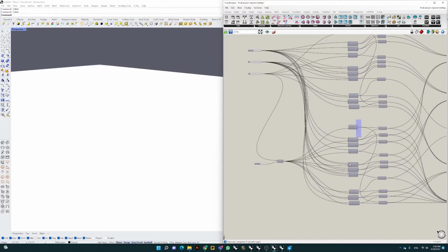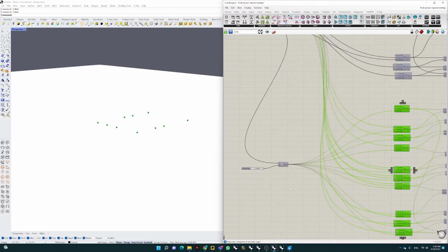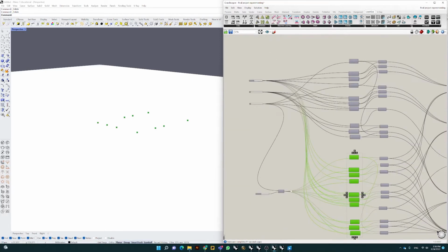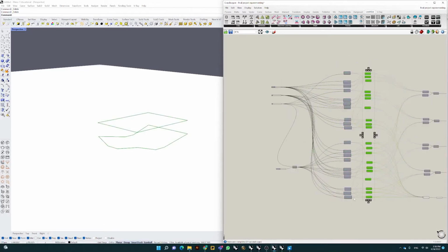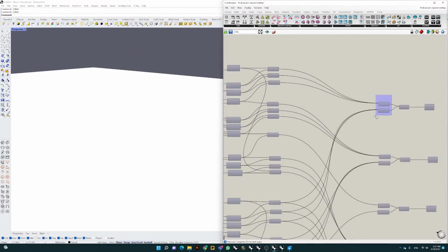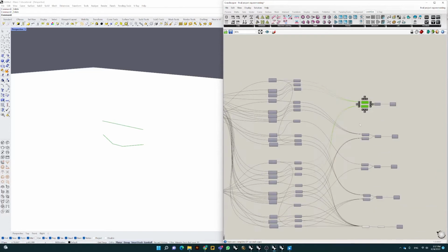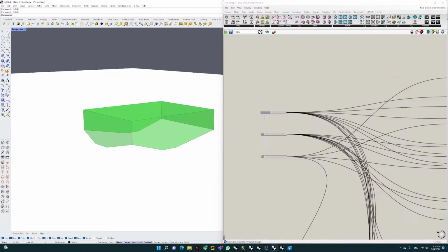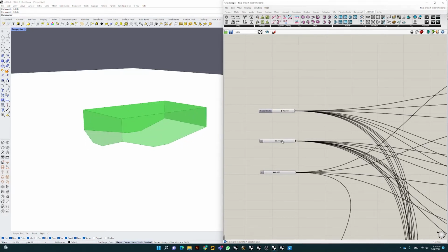And then for the bottom part, we also use the same method, but for the z-axis, we actually took the z parameter and then multiply it by 3. So there is going to be a relationship between the height of the building and the height of the openings on the mass. So as we can see them all together, these are the lines generated by the points. And then I started lofting between each edge, so we can get 4 different facades and a ceiling. So at the end we will get something like this, which is controllable by these parameters.